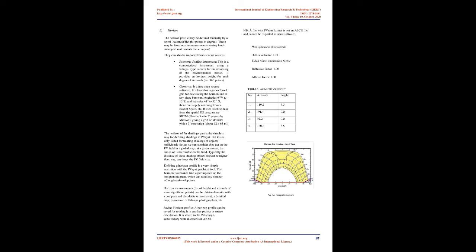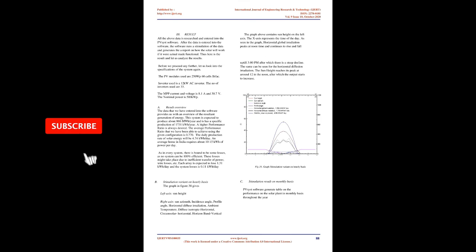2. Ohmic losses. Definition: the ohmic resistance of the wiring circuit induces losses. E loss equals RW·I², between the power available from the modules and the power at the terminals of the subarray. The relevant parameter for the simulation is the RW value, which is an equivalent resistance as seen from the input of the global subarray, i.e. the set of MPPT inputs defined in this subarray. You should define one RW value for each subarray in your system. Global wiring resistance, 7.23 mΩ. Loss fraction at STC, 1.5%.